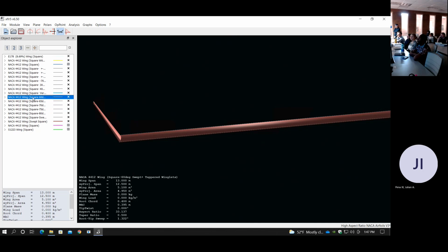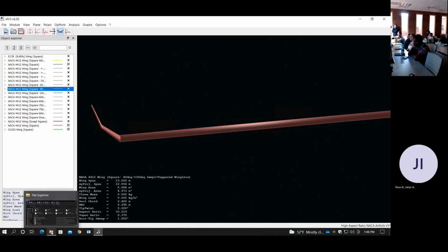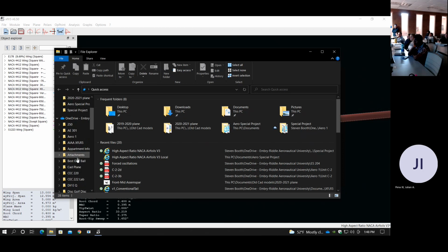And then I decided to have multiple airfoil sections as part of the winglet. So raking it almost. Yeah, trying to smooth out the curve in a way. I was just preliminarily trying to figure out if this is a better design than just a straight winglet. Then I recorded the CD, the induced drag values. Let me pull them up real quick.